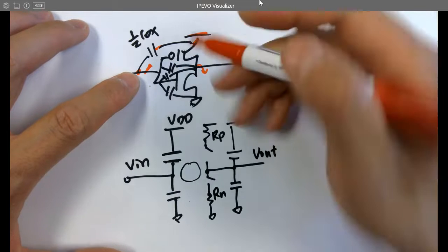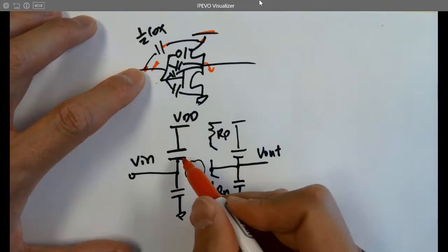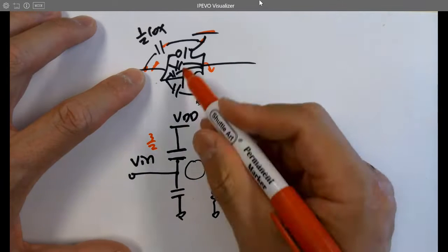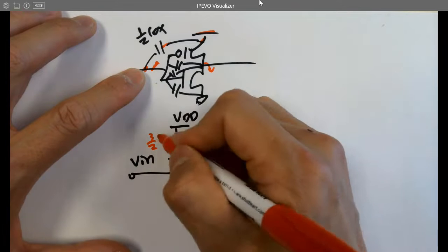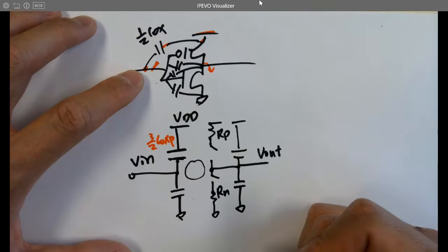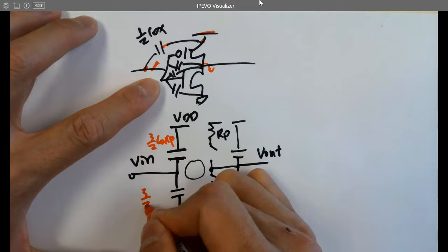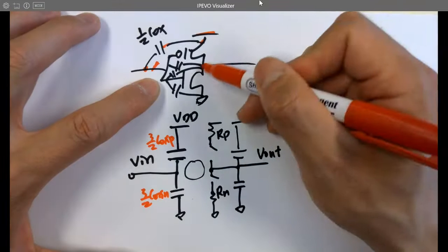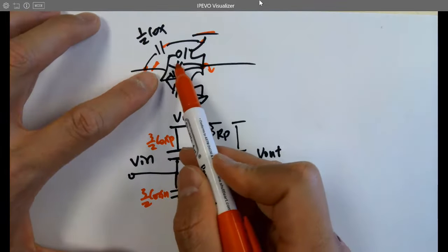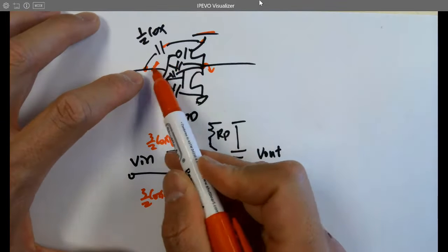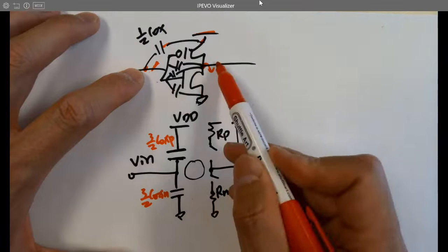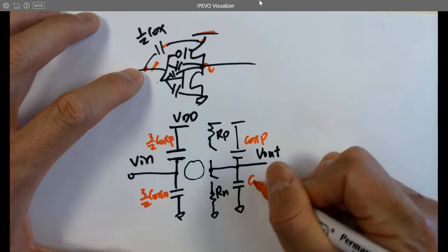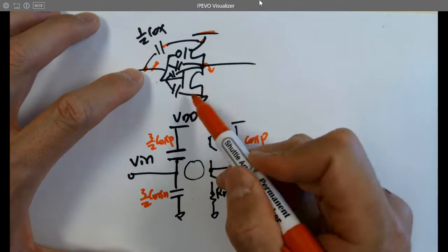Okay. So what is this one? The model. 3 halves, right? Yeah, combine them. There's just one, right? Cox P, right? Yeah, same for the NMOS. And because of the mirror effect, as the output, this capacitor is being divided into 2. One here is for 1 Cox P, and the other side is another Cox P. This is Cox N for the NMOS.